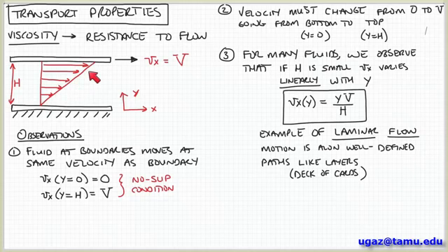The opposite case is what we call turbulent flow, where there's less order or more disorder to the motion. You have not only motion in the forward direction, but you have motion in the tangential direction, lateral to the flow. And this motion has a complex characteristic that's hard to describe. So this is an example of laminar flow, what we've shown here.